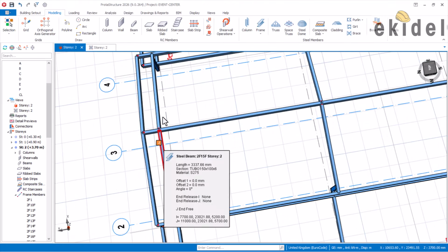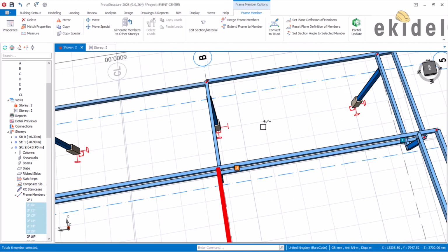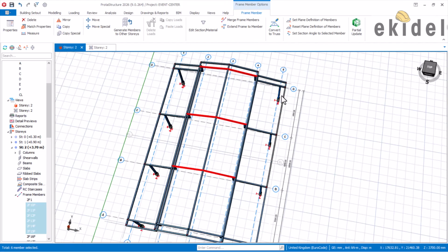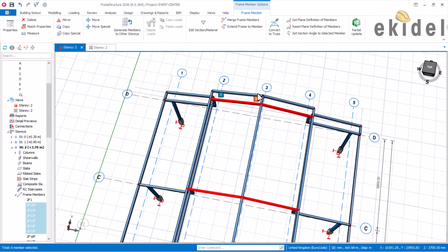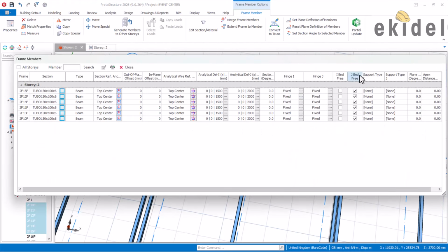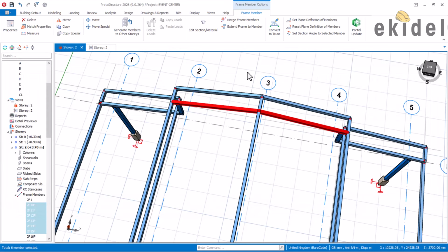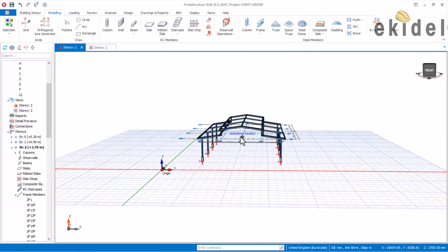Click on these beams now to remove the cantilevers on that face. It's not meant to be like that. Click here, and then come again here. Okay, just that face alone. Then come here, right click, properties of it. Come here, no cantilever. Come here, no cantilever. Say yes, that's fine, and then say okay, that is fine. Then we have this now having this. So we have successfully modeled that.